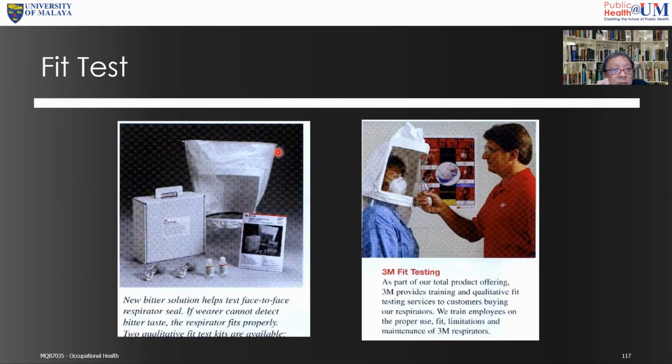So the qualitative fit testing is based on the person to identify the chemical. The other one is quantitative fit testing, where you basically measure the air after you fit, same like what happened in your nose. You put a measuring probe into the mask to see whether any chemical is collected or not. So it's called quantitative fit testing.